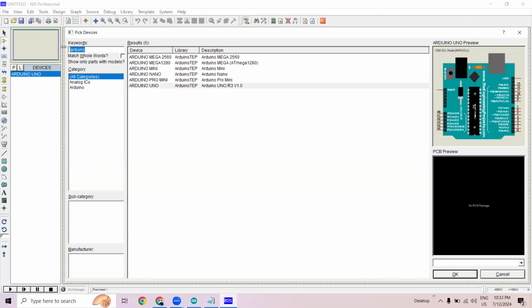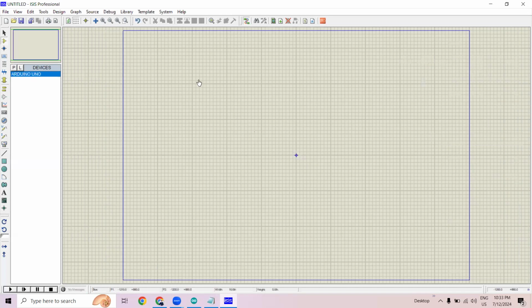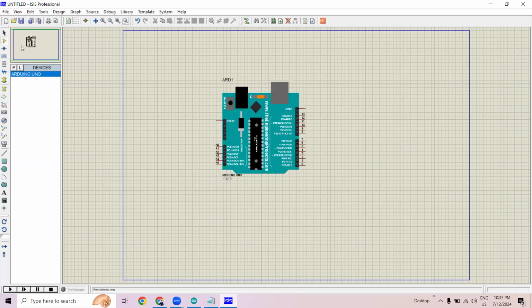And we are not going to use any predefined keypad. We will make our own keypad with the help of buttons. So let's write 10 numbers, 0 to 9, which means we need 10 different buttons. And to print the data, we need one 7-segment display. So in total, we need 10 buttons and a 7-segment, that means 17 pins. But it is not possible with Arduino Uno, because in Arduino Uno we have only 14 digital input output pins. So it wouldn't be possible to connect all 10 buttons and the 7-segment.